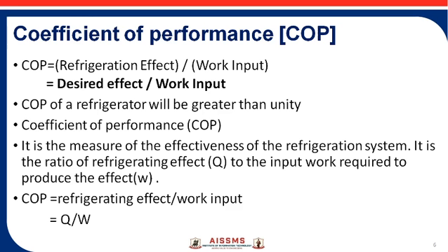We should know how we can measure the performance of a refrigerator. We measure the performance of a refrigerator in terms of the coefficient of performance, like efficiency. The coefficient of performance, that is the COP, is the ratio of the desired effect to the work input, or the refrigeration effect to the work input.